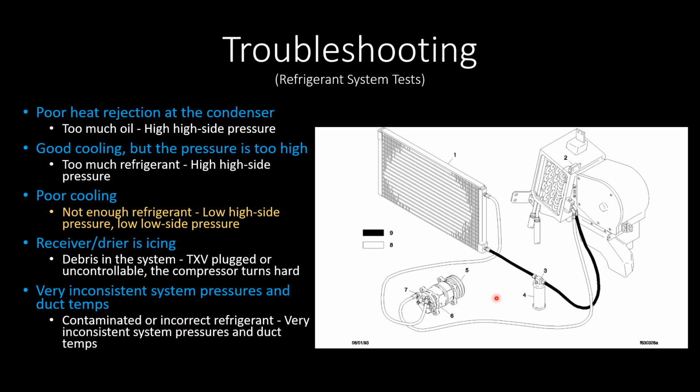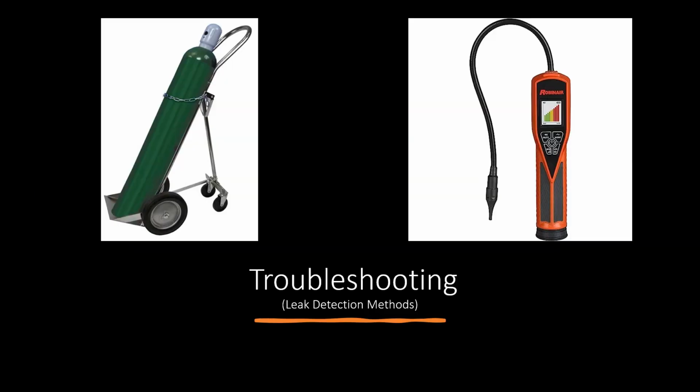So this is pretty much what you're going to end up with once you do this refrigerant test. If you don't need to get to this point, then you're probably okay. Typically, after the initial inspection, you're going to have an idea of where the problem is. But if you don't have an idea of where the problem is, that's when you would test the refrigerant system to its full capacity by leaving the engine hood open, by leaving the doors open, by making sure that the air that's coming into the system is the hottest air, which is the outside air, and then just understanding what you're doing when you're doing the test for the system.